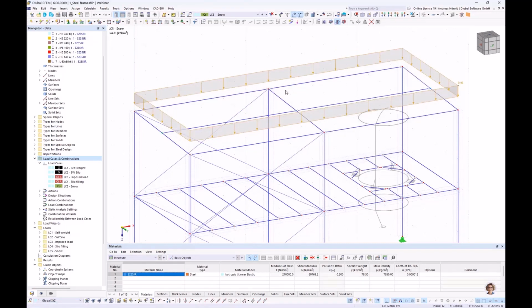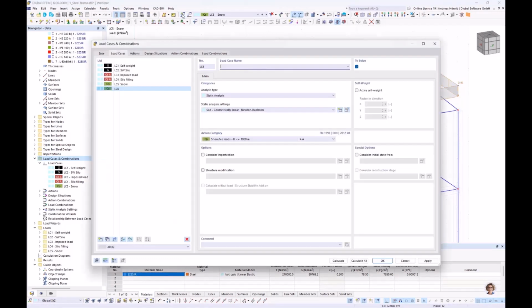So then we create the next load cases. I go to new load case. We would like to consider 4 wind load cases: the wind in plus X direction and the wind in plus Y direction, with wind pressure and wind suction.